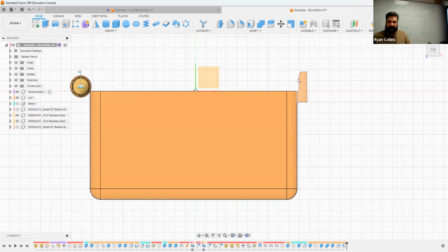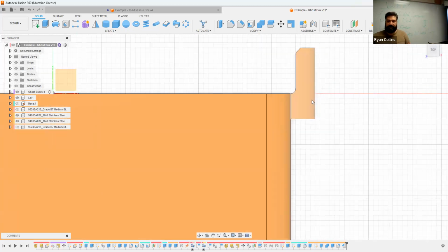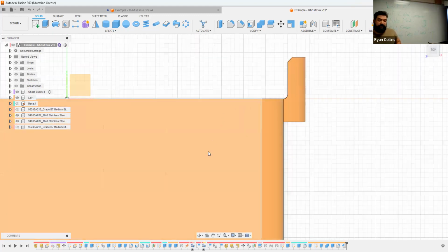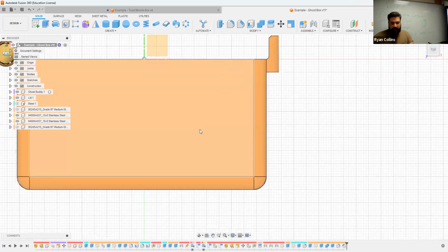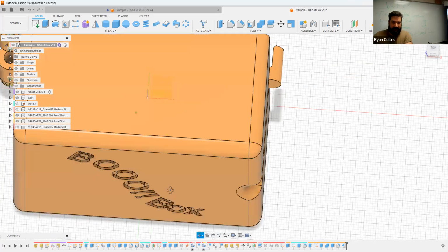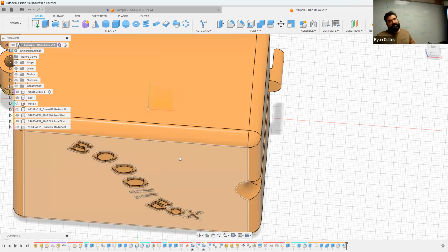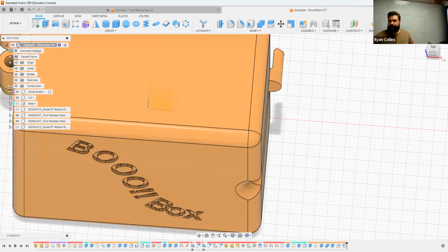Now, all your layering would occur. Yes, it would still layer across your lid here, or your little catch. That creates somewhat of a potential weak point, but you're not bending the latch off to get it to pop off. You're just flexing a little bit. The base will print nicely against the bottom of the printer. You're all set. And there you go.